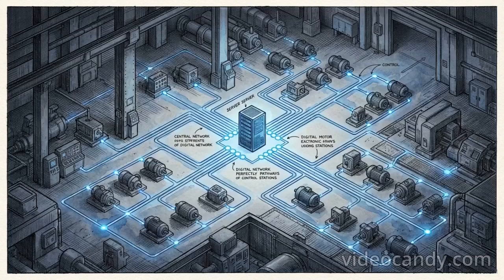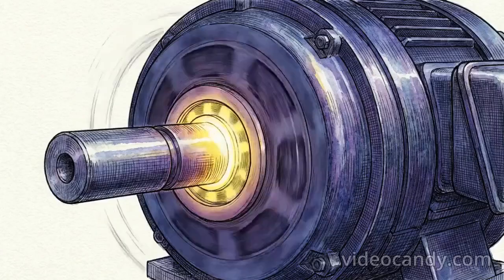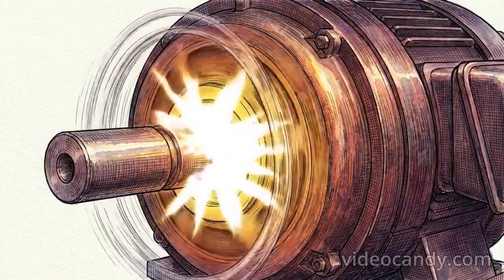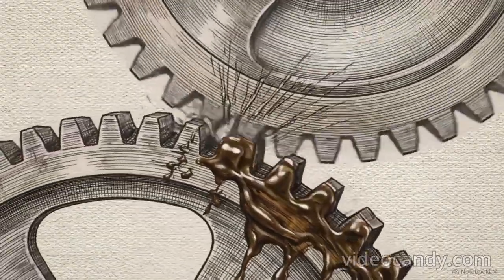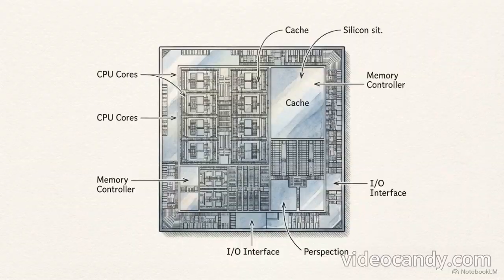For decades, the complexity of AC control made it prohibitively expensive. But the plummeting cost of microprocessors and high-power insulated gate bipolar transistors has made the AC volts per hertz drive the undisputed universal standard for nearly all new installations. In massive industrial complexes, centralized control rooms monitor and orchestrate thousands of these disparate drive topologies. Rectifiers, voltage source inverters, and Scherbius drives are all networked together to perfectly optimize facility-wide energy consumption.